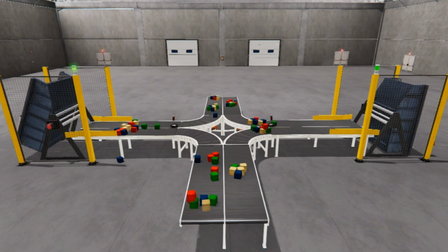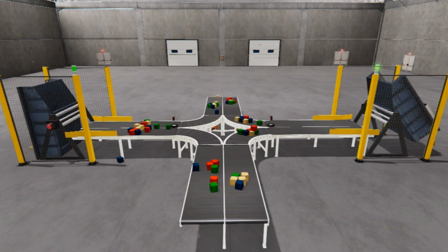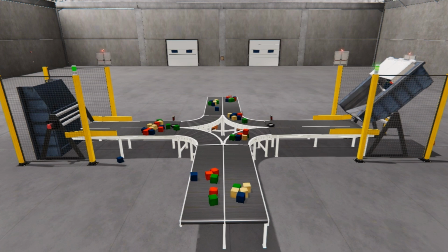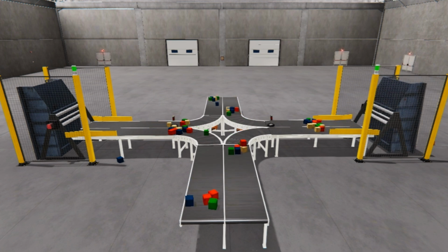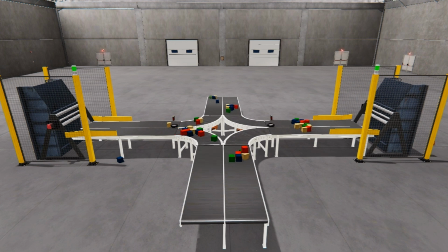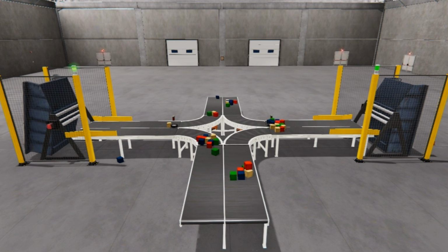When the first scan bit of the PLC turns on, the bit is set. It is also set by a hopper advancing and in the loading position. The reset of the bit will happen when the other hopper advances and is in the loading position. The operation of each of the box dumpers will be the same.